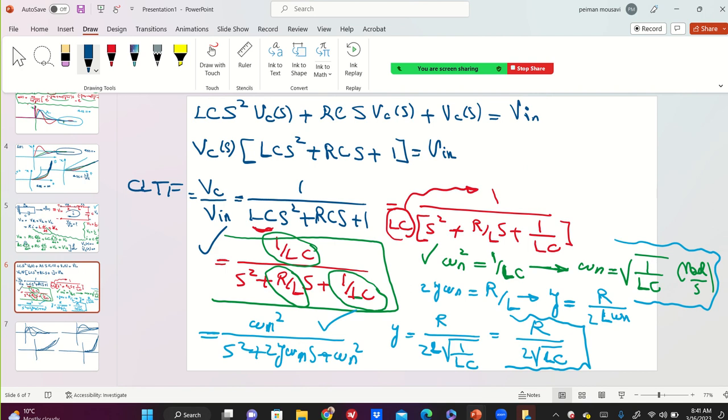I don't need to repeat it. And that's the powerfulness of this course. When you know that the RLC circuit is the mass spring damper, whatever I developed for the transient response and the steady state response is exactly the same.